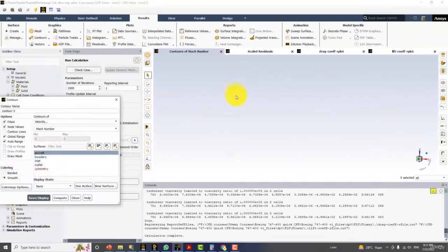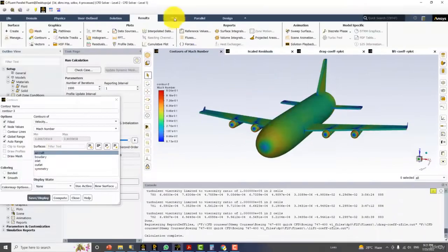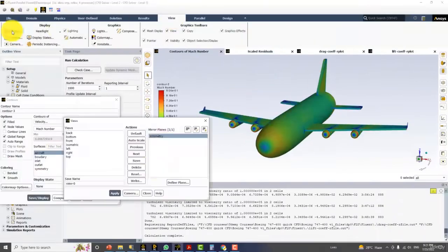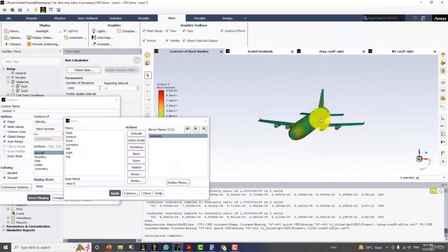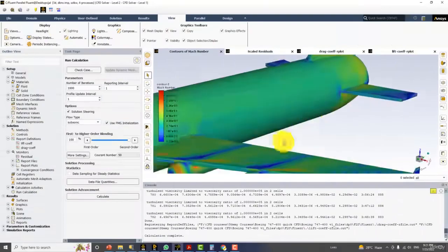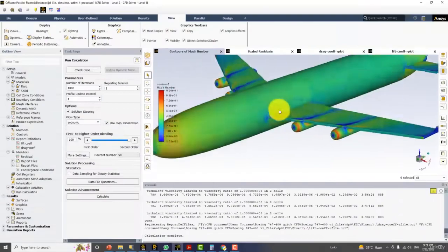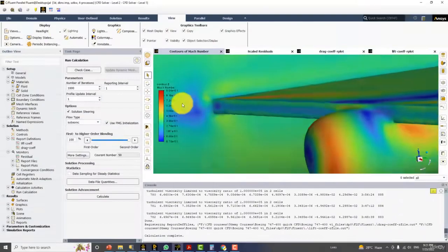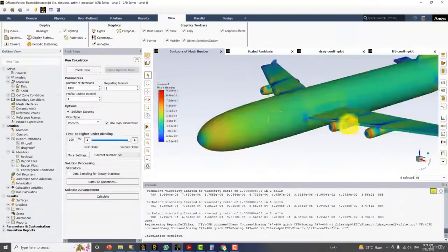on the aircraft, and how I made this full body: for that you have to go to the view command and click on views. If you uncheck this and apply, this will be a single body again. And if you select the symmetry condition and apply, this will make the full plane. And now if I see, this is not the exact geometry of the Boeing 737, and not the wings as well. The wings are straight rectangular bodies, but for the actual wing we have some aerofoil shapes.